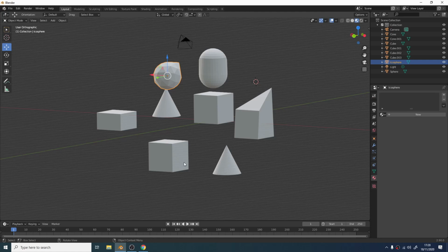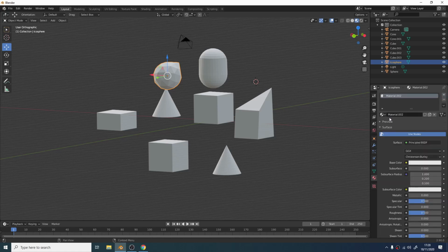To color objects is also very simple. We go to the material properties. Then we click the plus button in here and the plus sign for this section. Then the Material tab opens. Then we go to the Base Color tab, then click on the color. We choose what color we want. Then you drag this part and we overwrite the object that we will color.